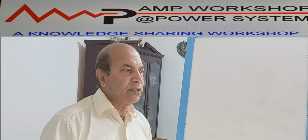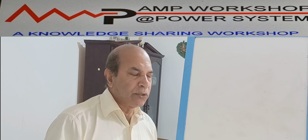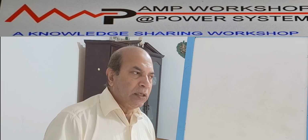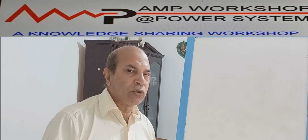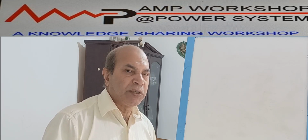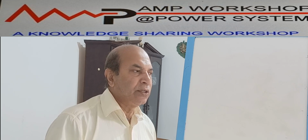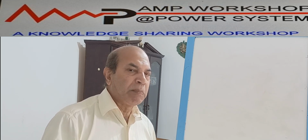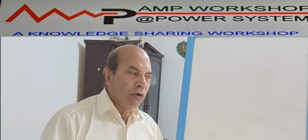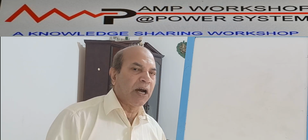Now for the rotating equipment sequence impedance, we will be developing the same way as that of non-rotating equipment. The only difference in the case of rotating equipment like generators is that in the network there will be a voltage source, because a generator is producing voltage unlike the other loads. So that voltage source will be present on each phase of the generator. And the second difference is that the generator will be producing power to outside, while a load is taking power from outside to inside. The direction of the current flow will be different.